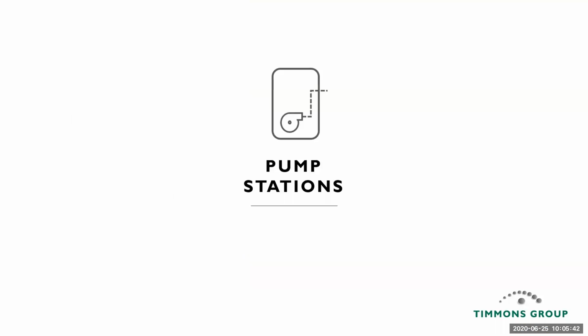Now, components of pump stations. We've got a holding tank we call a wet well. Obviously, there's pumps, and typically in a pump station, you'll have at least 2 pumps. That's not always the case. Smaller stations will be what we call a simplex or a single pump, but generally speaking, wastewater pump stations will have at least 2 pumps. The pressure pipe we call force main.